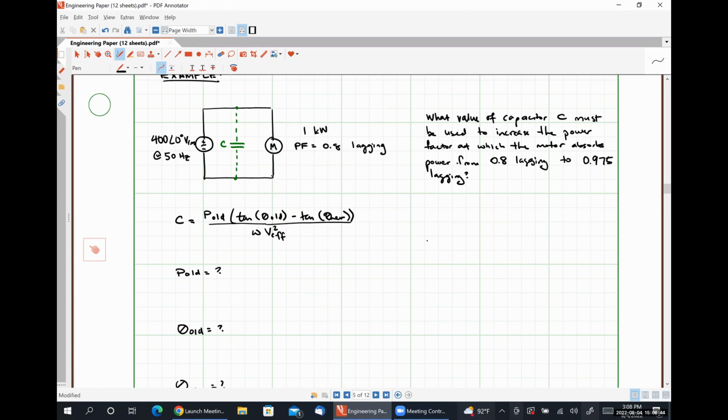So nobody's saying much of anything. So let's start with something that I think is pretty straightforward. V effective in this case is the voltage drop across the capacitor expressed as an effective voltage or RMS voltage. Since our capacitor is literally in parallel with our voltage source, I believe very strongly that V effective is 400 volts RMS.